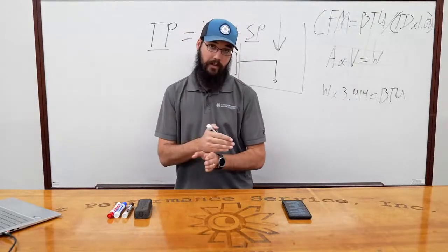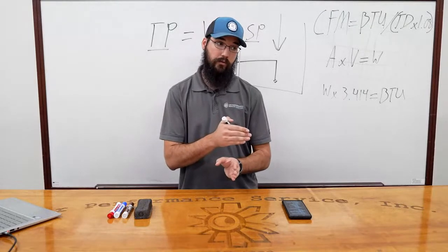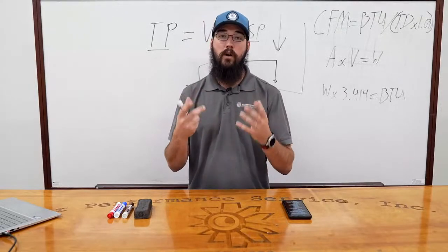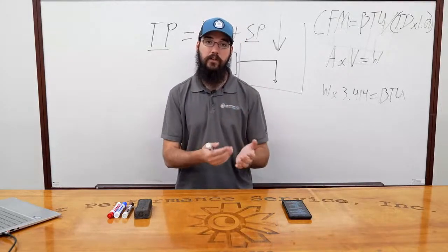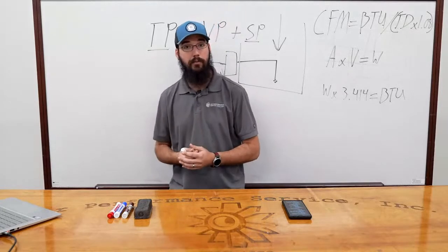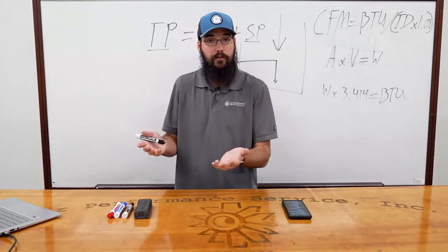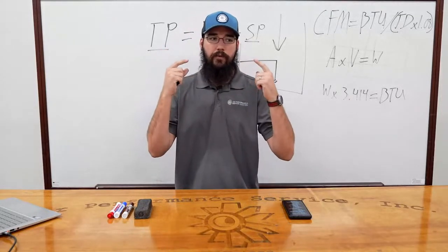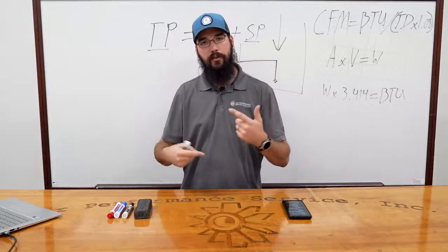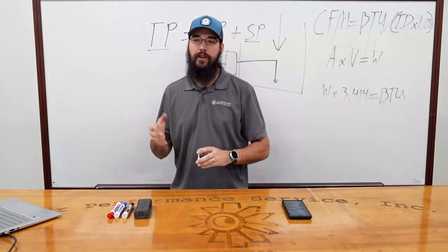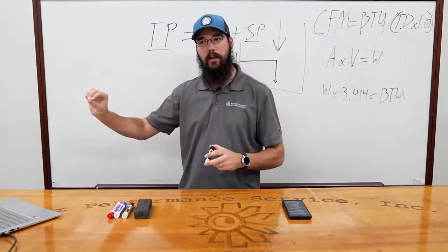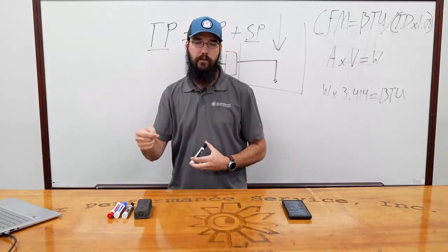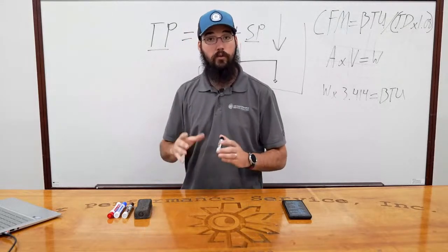And at that stage, your first thought is, okay, well, if you're walking up to troubleshoot, you're going to see the low saturation, but you might see your superheat still at 10 degrees or 15 degrees, right? And in your mind, that's going to cause a conflict, because if you only learn procedures and you don't understand what's actually happening, then you may rule out airflow in your troubleshooting, strictly because your superheat looks okay.